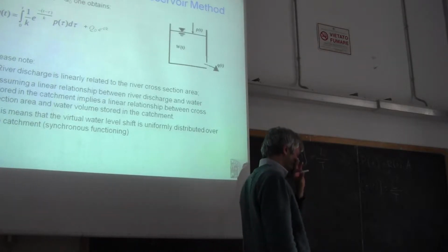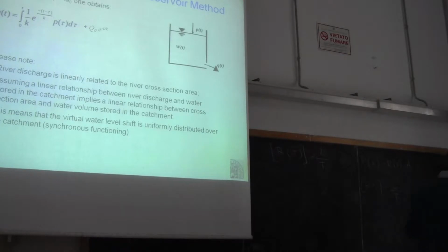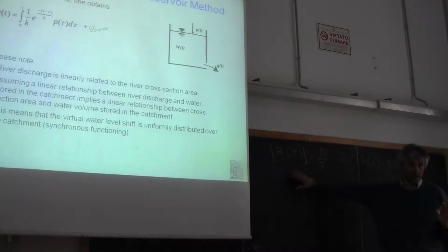Yeah, this is a good question, but it's not related to the meaning that RT and PT have. So the question is, once we multiply the rainfall depth over the catchment, so we accept that this is a rainfall depth per unit time, once we multiply it by the area of the catchment, do we obtain a reliable estimate of the rainfall volume over the catchment per unit time.